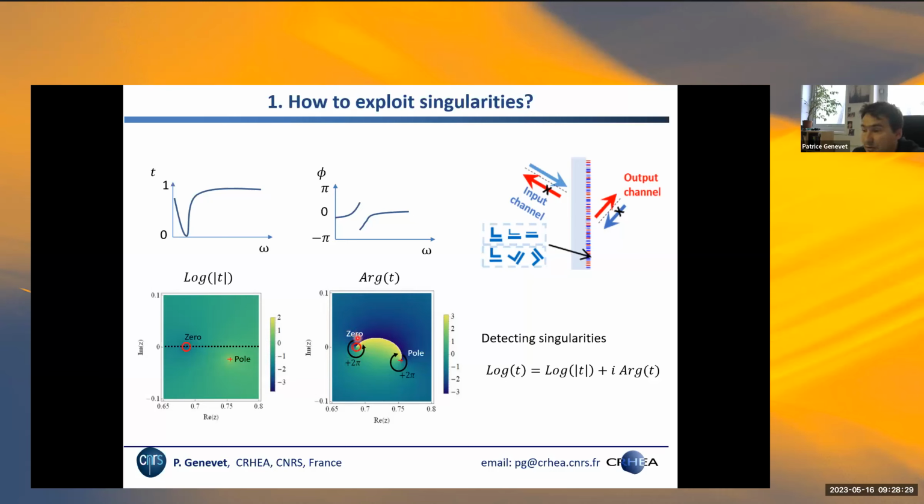And these are very important, and I call the zero the zero and the pole the divergence of this law. Why is it important? Because if you do a normal plane wave excitation, sometimes you see a feature here that goes to zero in your transmission coefficient and you don't know where it comes from. It comes simply because you bring the zero of your transmission complex omegas to the real frequency axis, and so you can observe it, right?